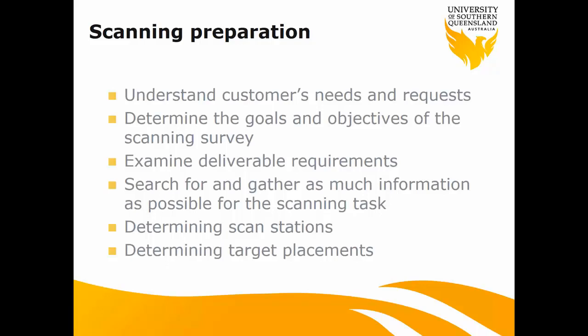Or you may use extra equipment, for example a GPS receiver or total station, in order to get some control mark positions for the purpose of georeference.